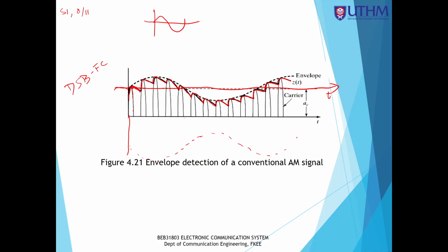So this is at point D. You're going to get a sine wave centered at the x-axis. Capacitor C2 removes the DC voltage.